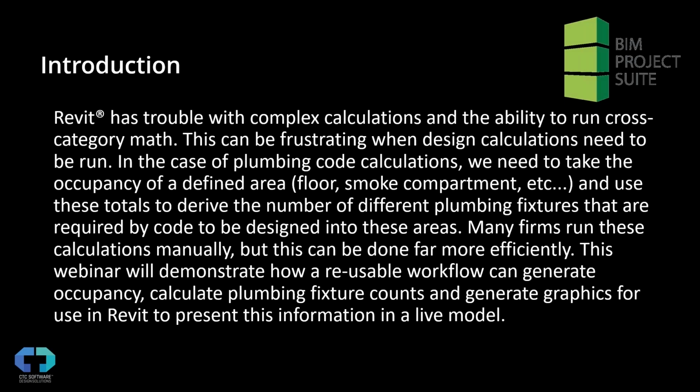But we can do this incredibly far more efficiently by using some tools that we're going to talk about today, which is Spreadsheet Link and Schedule Excel. And in today's example, I'm going to take you through the settings on exactly how to configure this and how you can calculate plumbing fixture counts. Now, if you're doing something else, maybe a little similar, maybe a little different, we're going to go step by step through this process.